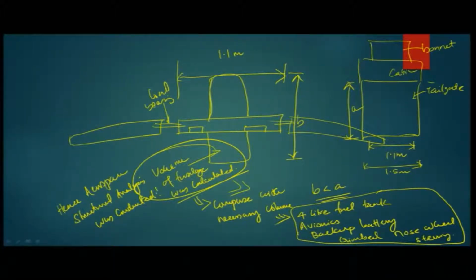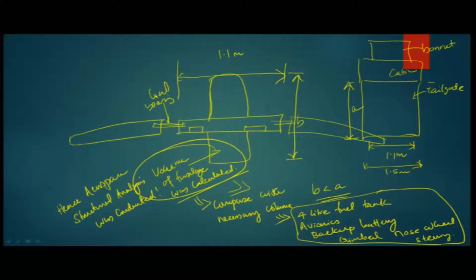We studied whether this connector in between has the capability to take the load, and it was found that rather than having this, it is necessary to have a connector throughout the length, which is bolted onto the entire central piece of the wing, and then onto the connector these wings will slide in. So this joint was designed as a slide and snap fit.